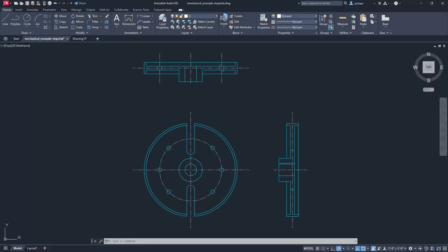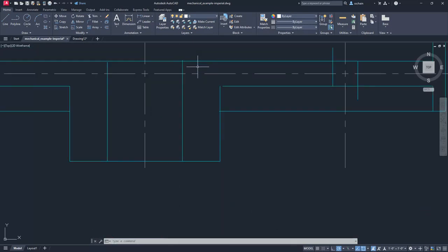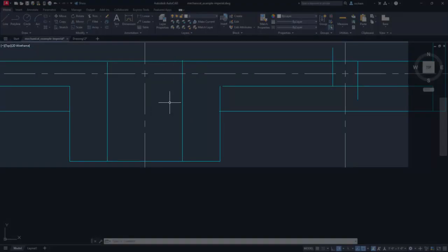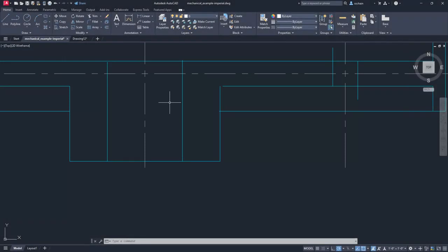of another line. In this case, with this drawing zoomed in, you can see the overlapping lines and irregular line lengths. This is an example of a drawing that was not created using object snaps. Without using object snaps, drawings are much more likely to be inaccurate. When the object snap function is turned on, it becomes active as soon as a drawing command does.